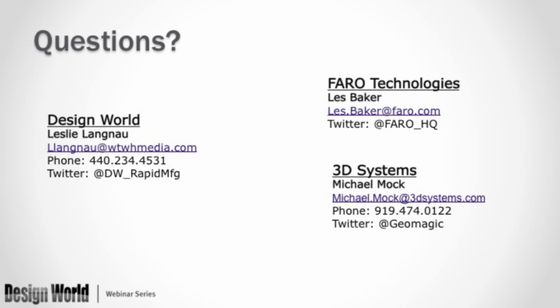Okay. And Michael, this is a continuing question for you. With the 3D printing machine, was there support material that had to be removed? For this particular type of 3D printing, the full color printing, there's no support material. It's printed in a bed of powder. You might have seen one of the pictures that said it had just come out of the printer. It looked a little white. It had some powder caked on it. It actually supports itself inside that bed of powder, and there's no need for support material. You just have to blow off the excess powder from that part.